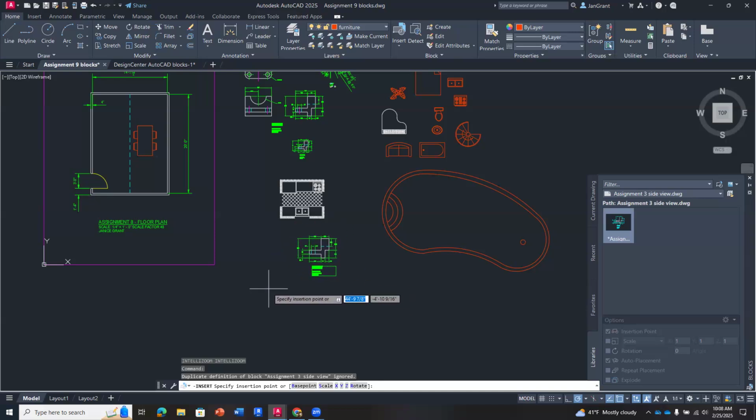So what I would suggest that you do is you open up those files and find out where the 0,0 is. You can just start a line and type in 0,0 like we did for this border and find out where the origin is, or look for this XY. That's where the origin is automatically. And then you could move your objects to that origin based on your insertion point, or there are a couple other things you can do.